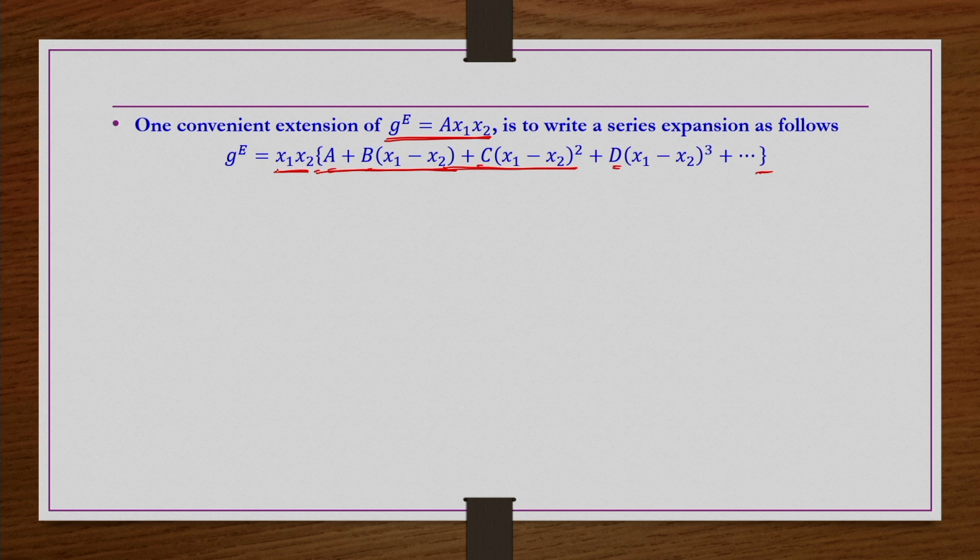And then we have seen when it is the 2 suffix Margules equation, ln gamma 1 is simply a x2 square by RT, and ln gamma 2 is simply a x1 square by RT. Mathematically they are clear, and we can realize ln gamma 1 and ln gamma 2 are symmetric activity coefficients, right. But when you add this second term b (x1 minus x2), the equation becomes the 3 suffix Margules equation.